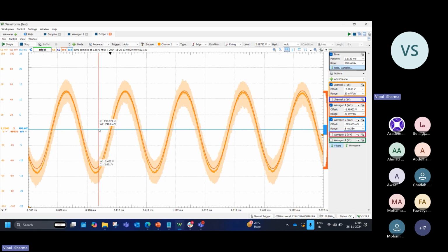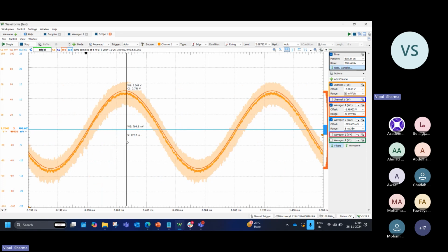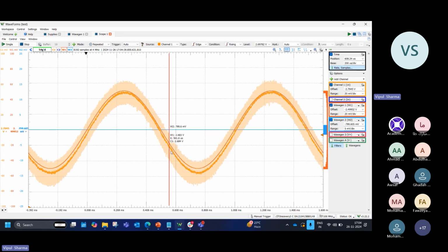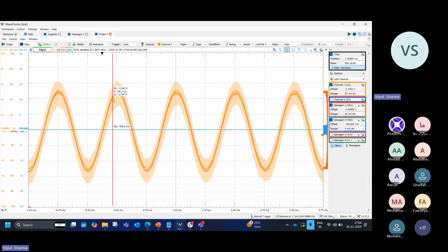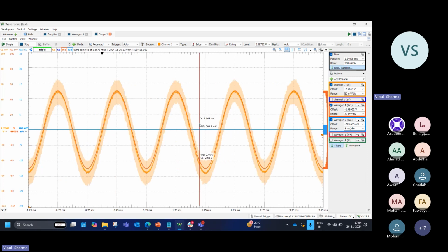And so source, what is basically the functionality of source follower? It just replicates the input signal to the output with the gain of 1. So that's what we are seeing here. And whatever perturbation you are seeing on this output are most probably noise. So there is some limitation, like you cannot do a very high fidelity measurement with this setup. But this is the basic purpose, like how my op-amp is working in which configuration, that can be easily verified.